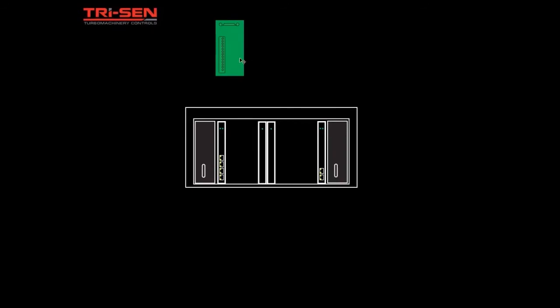So then we need a couple of term panels to communicate external I/O data into the chassis. So we have two termination panels shown here. Those allow us to wire up field wiring. Then between the term panels and the I/O modules, we need to add some I/O cables.